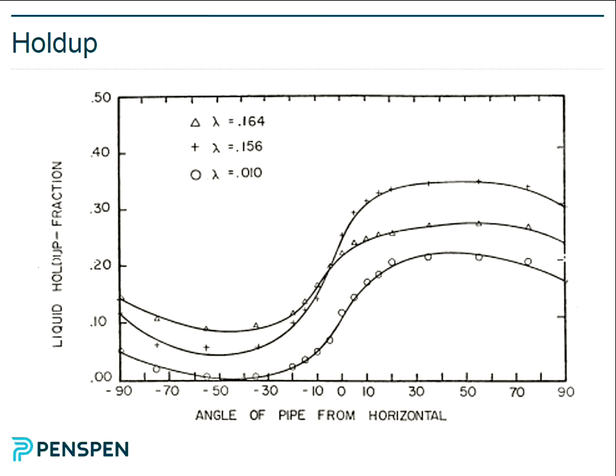Intermittent. Now we're talking about stripes in the vertical sense. So segregated, separate by gravity, and then intermittent, slugs moving along the line. So slugs and plugs. And then distributed, or the other term for that is homogeneous.